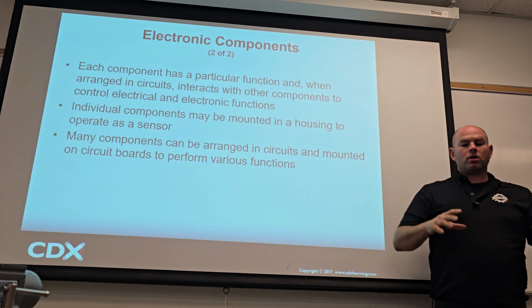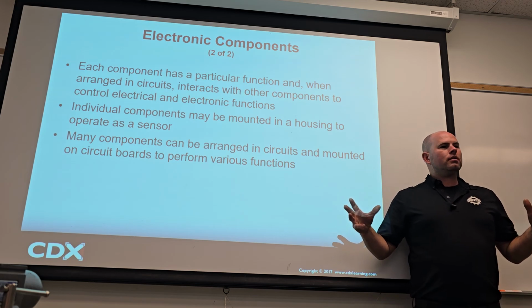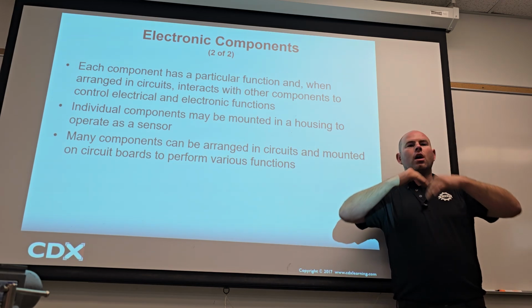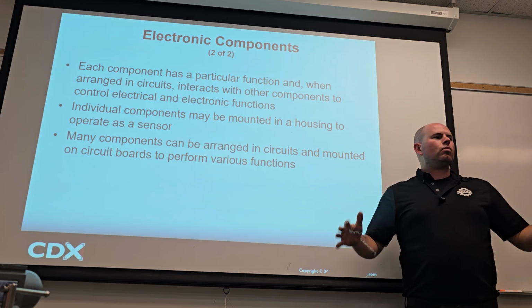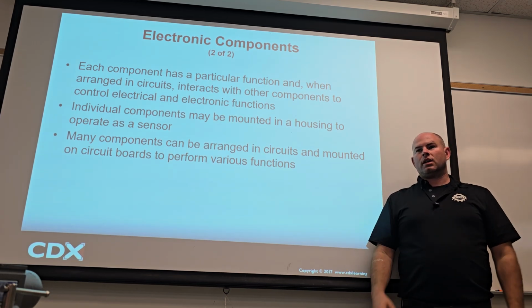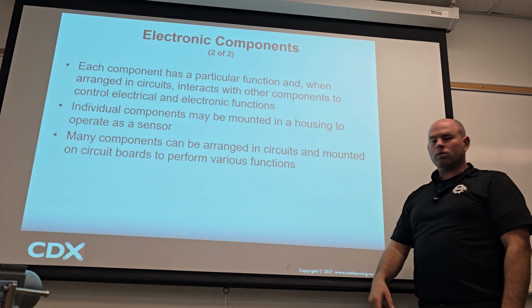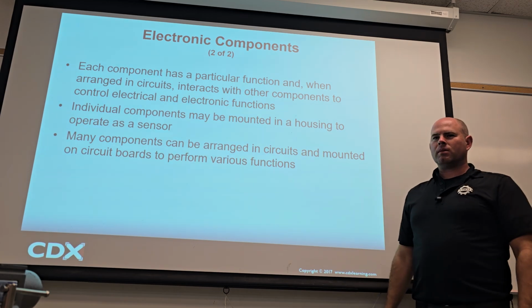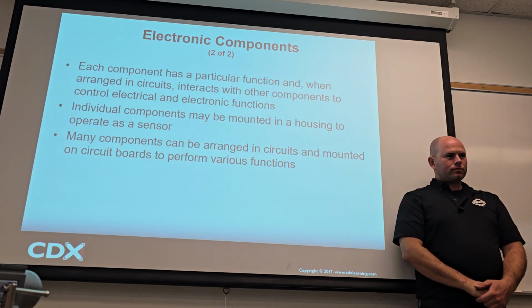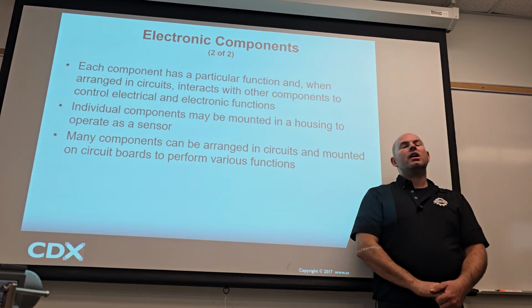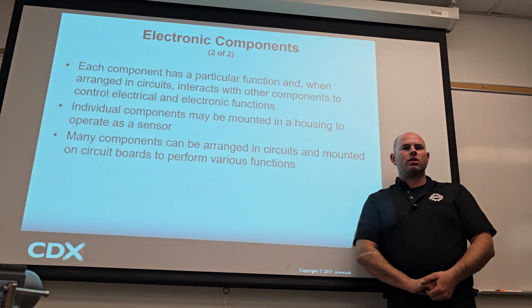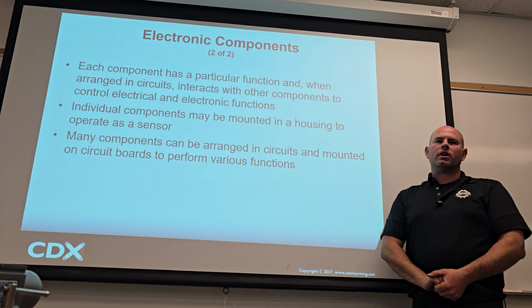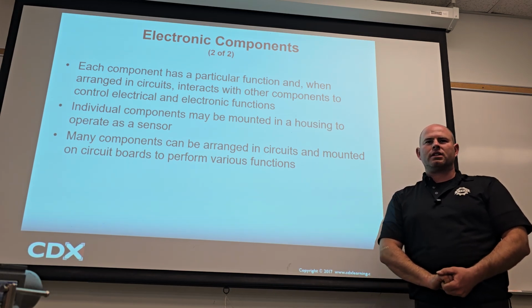So a computer could go completely offline, would you agree? Like a computer could not work at all. If that engine control module, that engine computer, didn't work at all, it wouldn't boot up, right? Like you go to your PC, you're trying to turn it on, it won't turn on. What do you think the symptom is? What do you think it would cause on the car? If that computer wouldn't even boot up, you think it would cause a code for a heated O2 sensor on the left bank sensor 1?